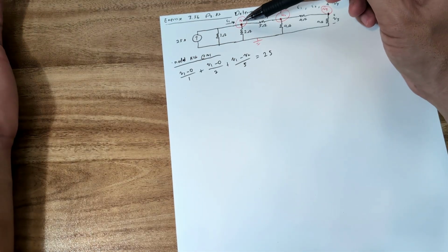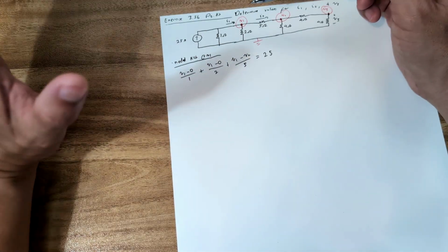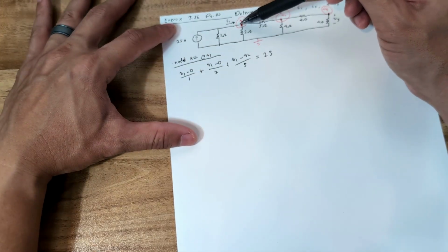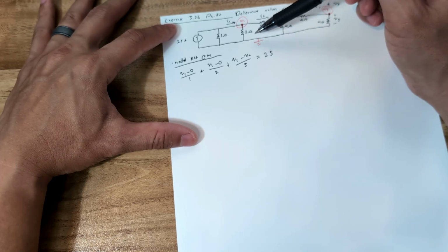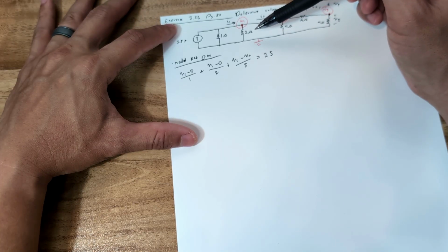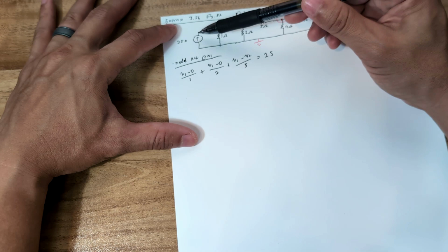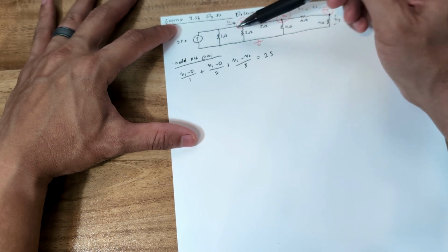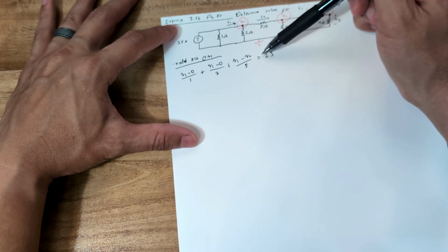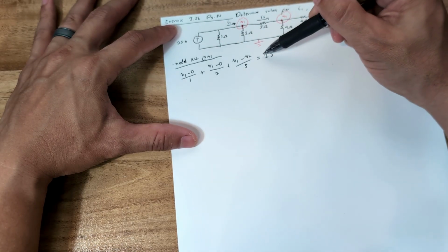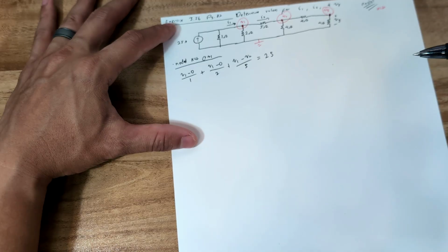It's probably not the case all the time, but for nodal analysis, you're always assuming that the current is going out of the resistors, equals the currents coming in from any independent or dependent sources. In this case, since it's coming in, this is going to be positive. And if this is going out, you would put a negative on this 25.